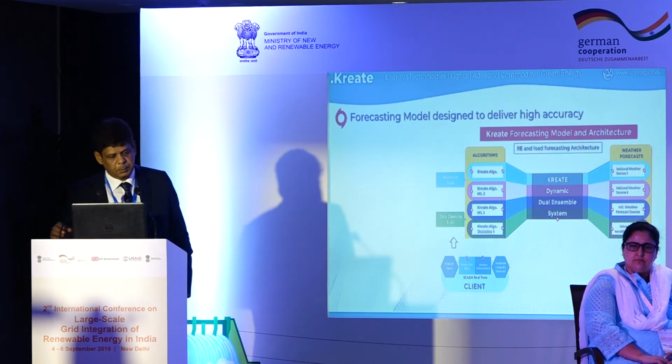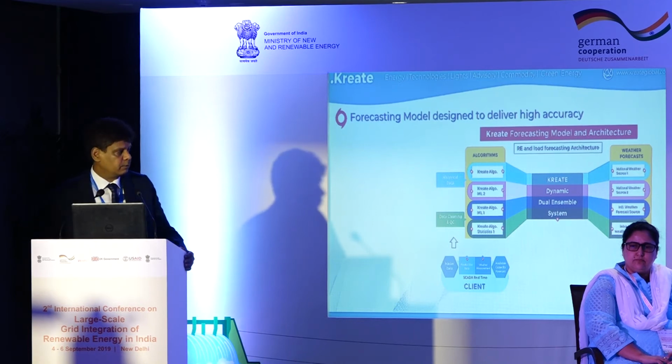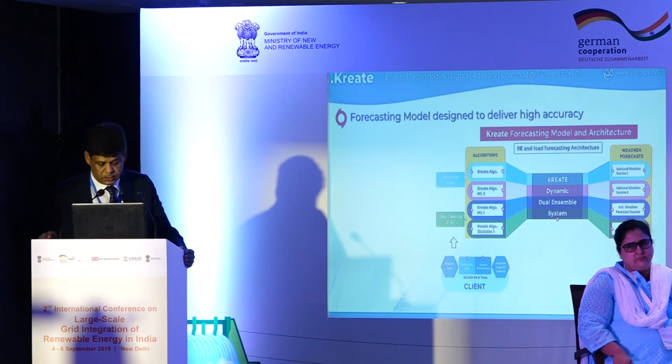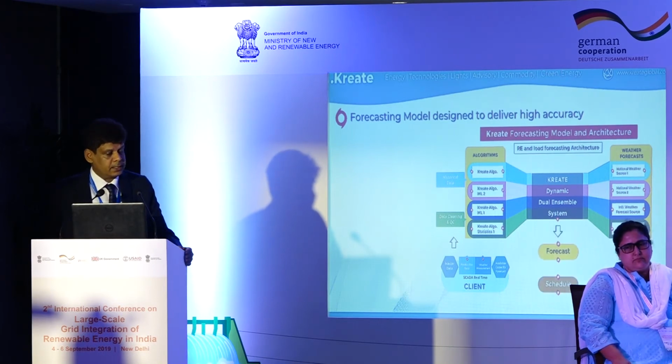based on the machine learning, it picks one, because to SLDC you can't give multiple forecasts, you have to give them one forecast. So you have to select the best forecast and then give it to them. And for the RE and wind, that needs to be given to the QCA, which is again given to the SLDC. And you need to continuously keep revising it based on the errors which happen, because the revisions are allowed, and you need to minimize the penalty for your generator or the client in this case. In some cases, we have taken commercial risk. So it's also to minimize the penalties which happen in case of a particular generating station. And then based on that, the forecast is created and the schedule is created.